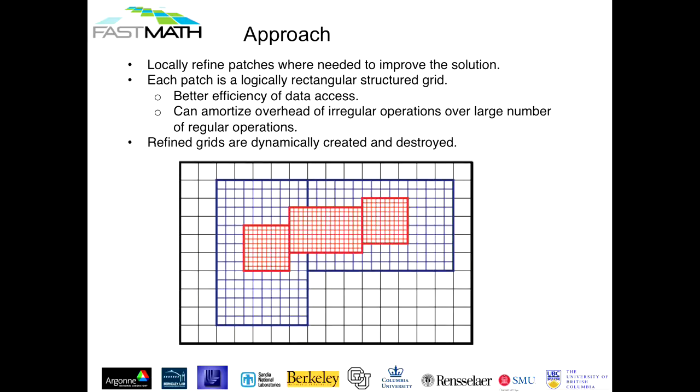To bootstrap yourself up, you first lay down your mesh, you throw down your initial guess, your initial solution, and then you already start running your tagging algorithm. When you run the tagging algorithm on level 0, it gives you level 1 grids. You run it on level 1, it gives you level 2 grids. And you keep going until you've met some kind of criteria.